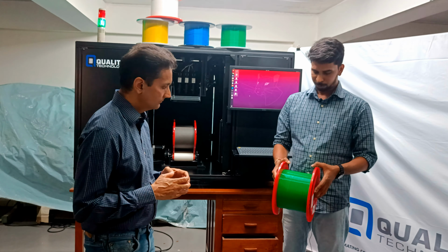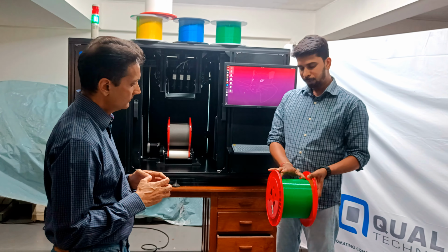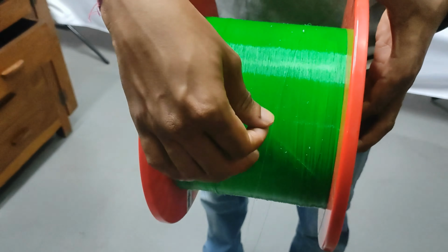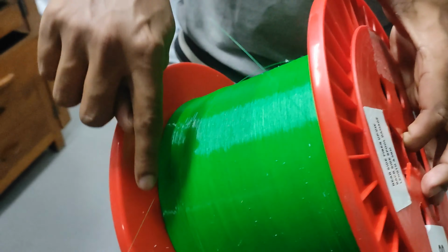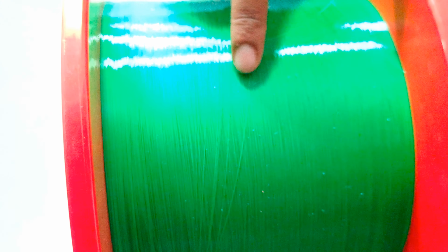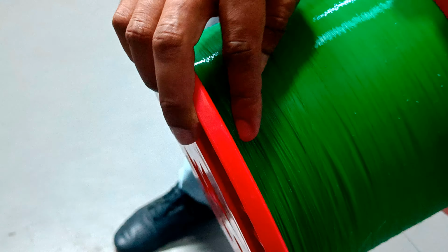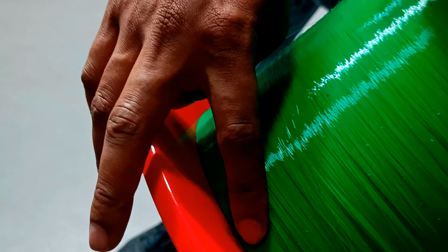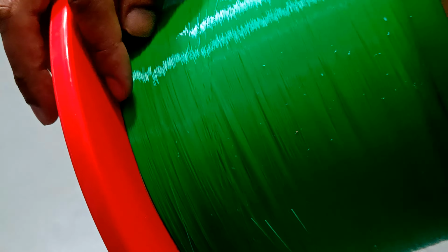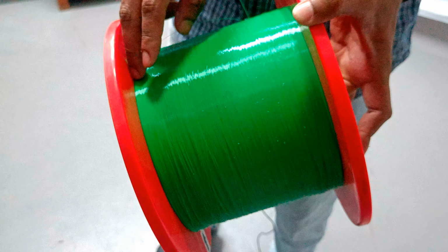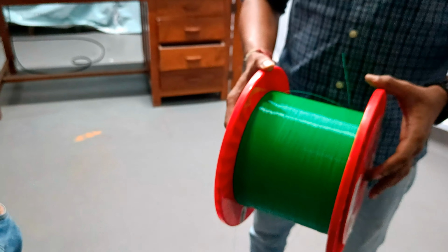In the fiber, we have multiple defects, such as these dust particles, which are undesired and should not be present in this fiber optic spool. Also we can observe some loose fibers, which are not recommended. Along with that, there is some bump in the winding. Okay, so it's not evenly wound. Yeah, it's not evenly wound. So when it's unwound, that might lead to some problem or some damage, which is highly undesirable.